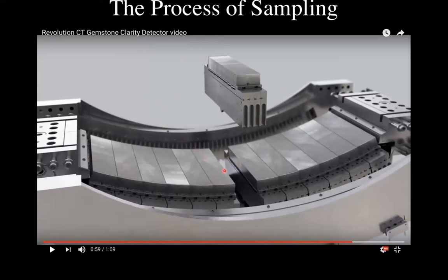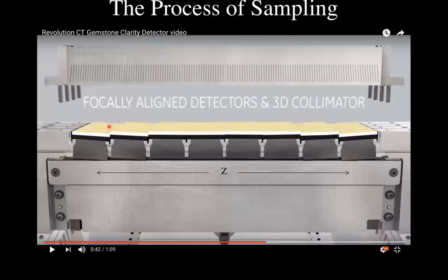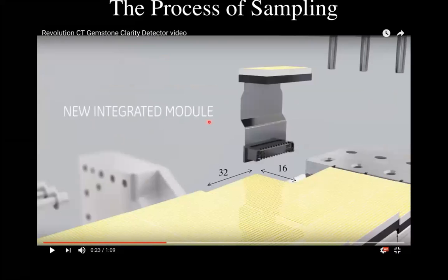And inside each one of these modules, we have a set of these little chips that have individual detectors on them, and they detect an X-ray, cause a flash, goes to a photodiode, which makes a voltage coming out, and that set of signals comes out of each one of these replicated chips. You can see it's plugged in here. This is where the electronic voltages come out. Here's the detector element itself. It's 16 detector elements this way, 32 this way, and they are separated by about 1 millimeter.